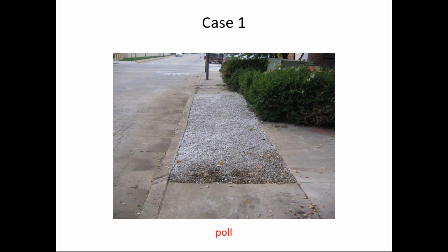I would say for the temporary traffic barriers, the concrete and especially the water filled, yes, for sure. For the channelizers, desirably, but I would say they're going to move so much or else be destroyed by the vehicle impact that it probably doesn't matter. Their main purpose is just to separate pedestrians from the vehicles. There's no intention to protect them from a crash, as much as we'd like to. To do that, you need the crash-worthy devices. But especially if you use the water-filled device, it's a good idea to have additional width to allow for the movement of that. But that could be considerable. That can be up to like 10 to 12 feet.